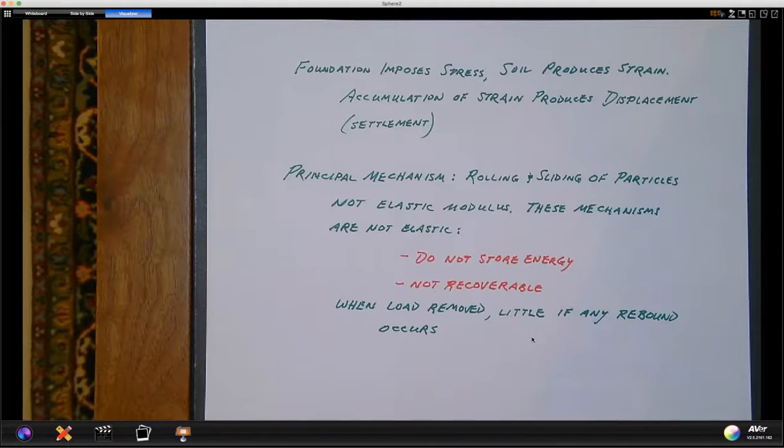They're, again, set up in a highly idealized, calculus kind of solution, very, very idealized stuff. And it'd be impossible to come up with solutions for every single possible foundation depth and so on. But as engineers, we just step in and cut that corner and say, all right, well, it's embedded 3 feet. So now we're 10 feet below that point of interest, which happens to be 13 feet below the ground surface. And that is not all that important for the calculation of this.